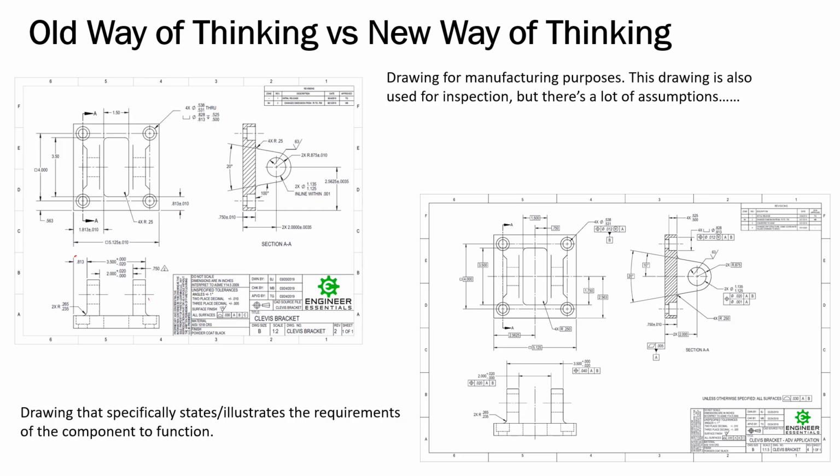This print over here, the GD&T print, in no way states that whenever they put this part in there, they have to put it in the counterbores to secure this and then secure those 4 holes. Like I said a while ago, it's not going to be that way at all. They could just simply put this up against the back jaw of their vise and then have a stop over here to the left side and slide the part up there. But they have to know, if they did machine that outside profile first and they're going to do this, they have to know where they're at and where they need to be.